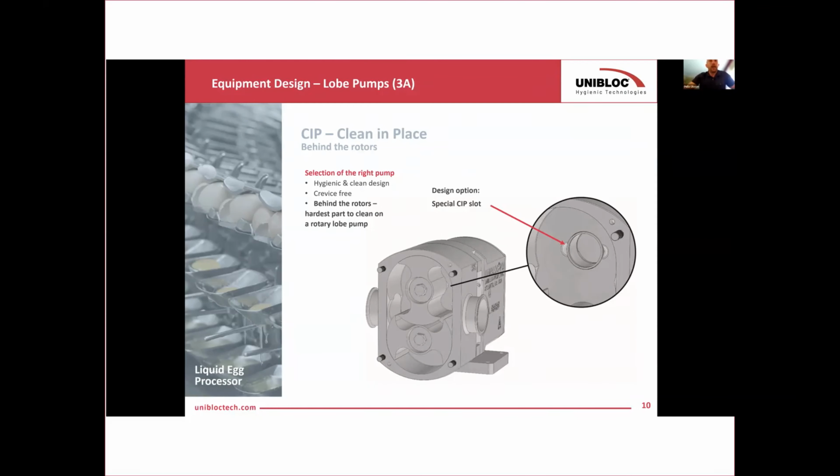They were using a pump with, again, a lot of crevices and super tight tolerances. And they were doing CIP, yet the USDA inspector did not trust, or could not validate, that the pump was being cleaned out properly. So the way they were operating at the time was to run the product, then start the CIP cycle.